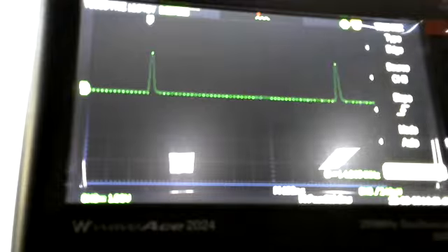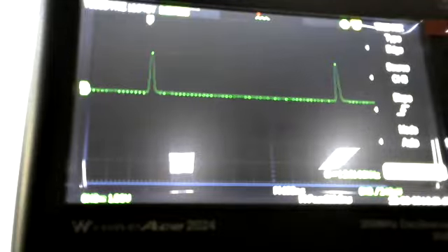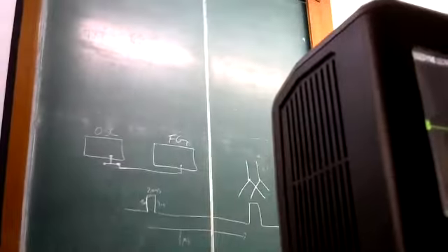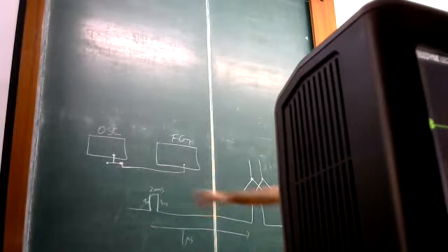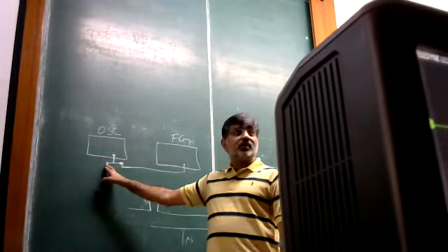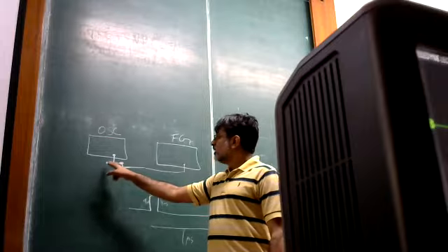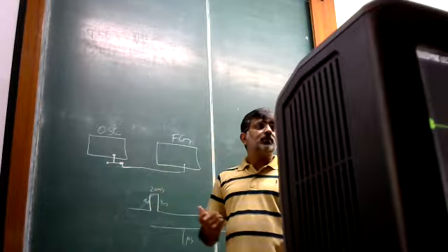There are questions you can ask about why this empty part. So remember, the T junction is not connected fully. If I go back to the diagram, this part is currently left unconnected, but it's not doing anything because this length of transmission line from here to here is very, very small.